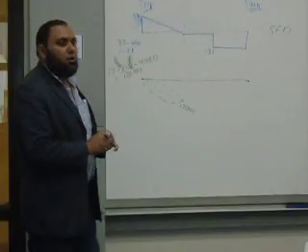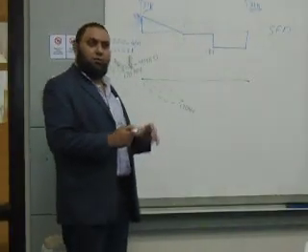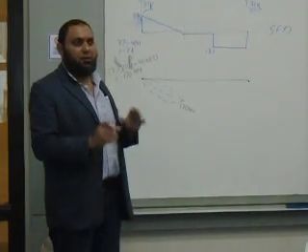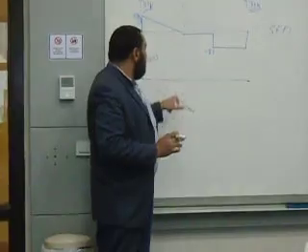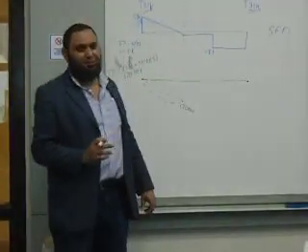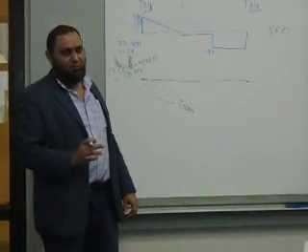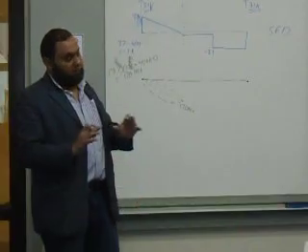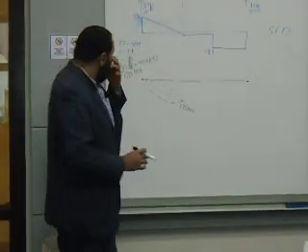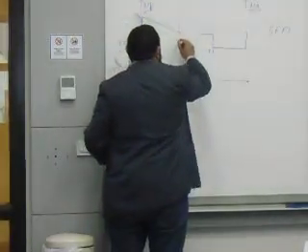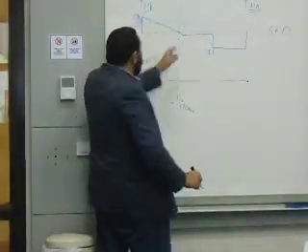Do we agree that because the relationship between the bending moment and the shear force is an integral relationship, at a zero shear you must have a maximum in the bending moment, or a minimum, depending on whether it is a local maximum or minimum? Okay, right? So we need to calculate this value. We need to take a section here.